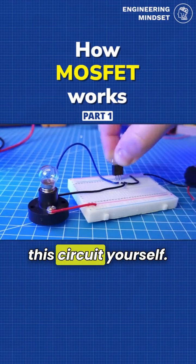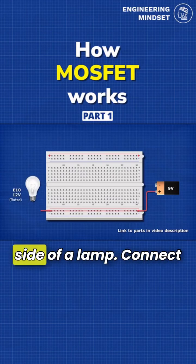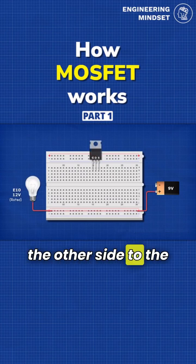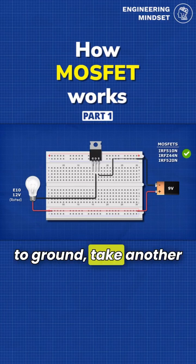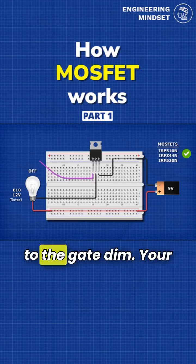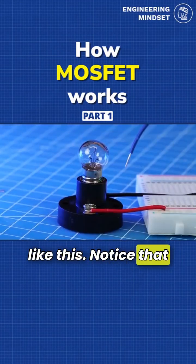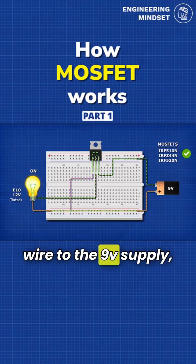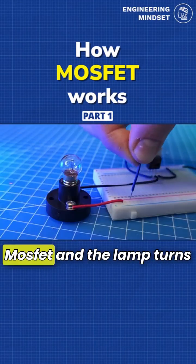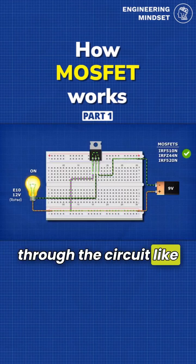Try and build this circuit yourself. Take a 9-volt battery and connect it to one side of a lamp. Connect the other side to the drain pin of the MOSFET. Then connect the source to ground. Take another wire and connect this to the gate pin. Your circuit should look something like this. Notice that the lamp is off, but if we connect the gate wire to the 9-volt supply, it will activate the MOSFET and the lamp turns on. Current is flowing through the circuit like this.